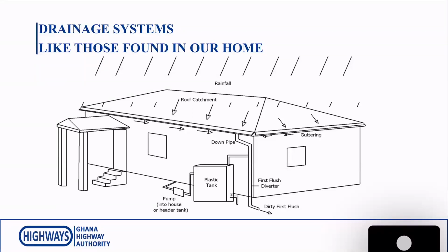Now, if we fail to meet these basic drainage requirements, it can result in pavement breakup, potholes, cracking, shoulder disintegration, base saturation, and eventually total pavement failure.